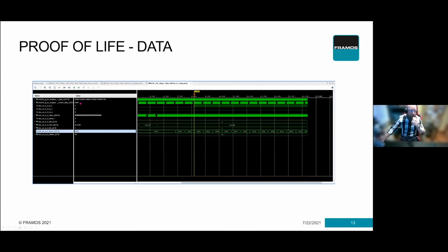So what we would normally do is have you place a sort of recording block within your FPGA code, put that into your system, and then run it up, and then we can see exactly what's going on here. So we can actually see if your data lines are correctly connected. We can see if they've been correctly configured in the transceiver configuration for the FPGA.